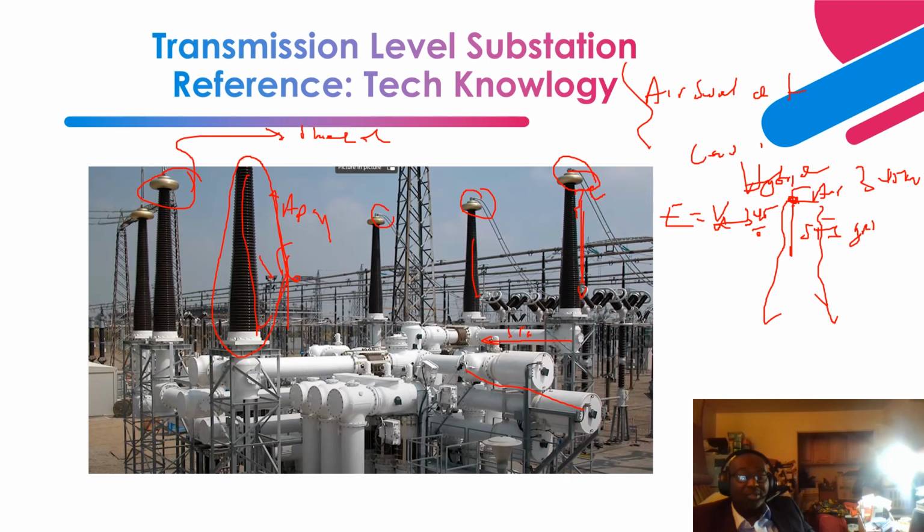as they call it, to grade the electric field that is found in this area. So what we are doing is forming different sizes of ring, stretching, increasing the distance D over here. The electric field is voltage over distance. So we are increasing the distance from a dot, which is just a connection.